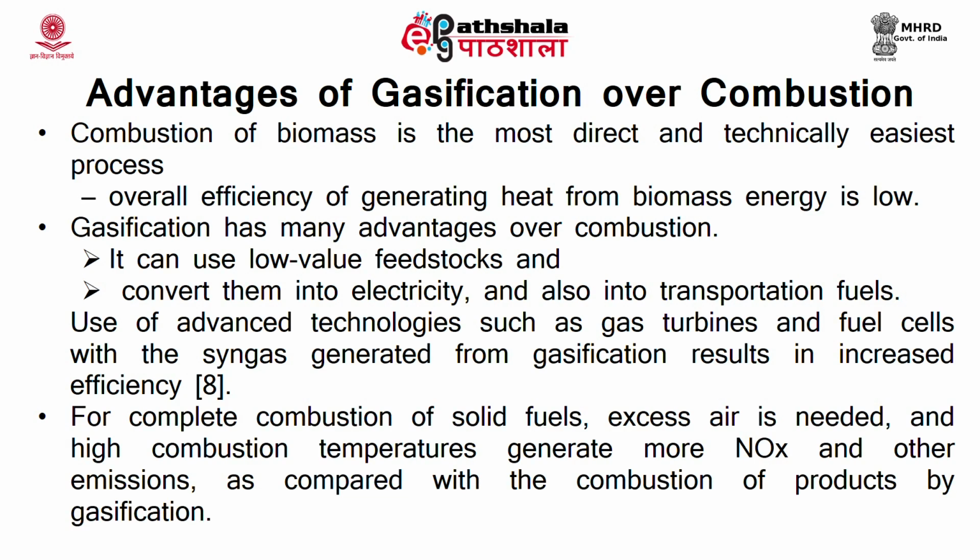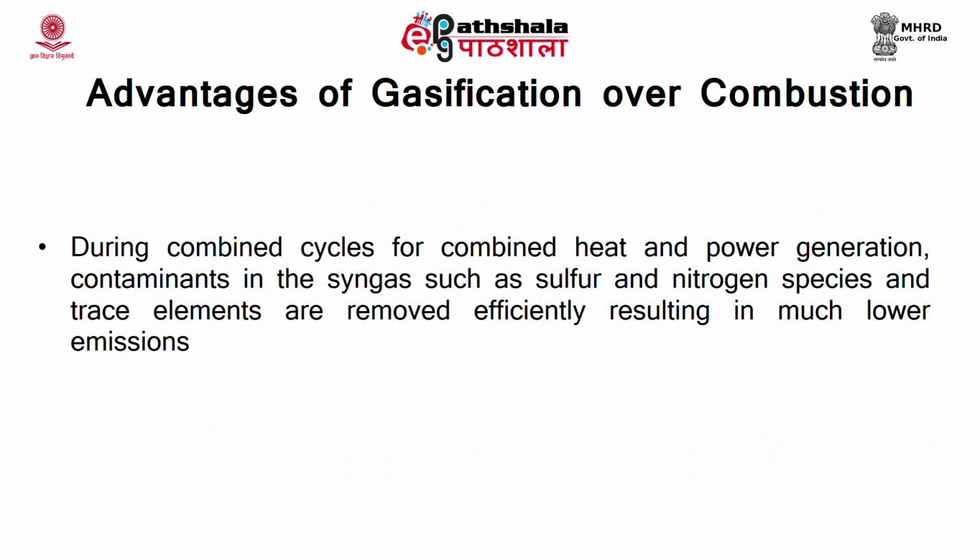For complete combustion of solid fuels, excess air is needed, as we have already told, and high combustion temperatures generate more NOx, or oxides of nitrogen, and other emissions as compared with the combustion of products by gasification. During combined cycles, where there is combined heat and power generation, contaminants in syngas such as sulfur and nitrogen species and trace elements are removed efficiently, resulting in much lower emissions in the case of gasification. So, gasification is advantageous over the combustion process.